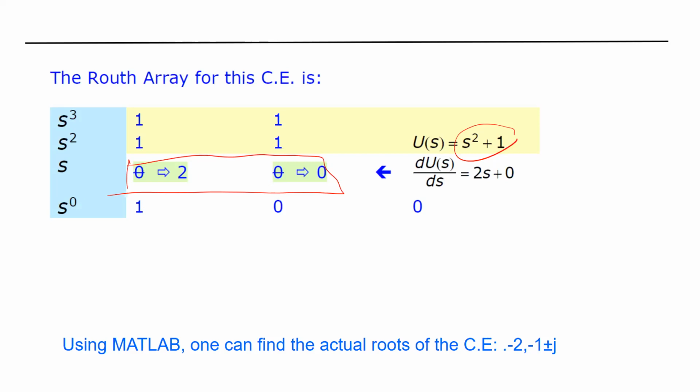But this method, as I said, is by trial and error. While if we go to the other one, in terms of the gain margin and phase margin, you can precisely calculate the gain which you can add to the system before it becomes unstable. Any question before we stop?